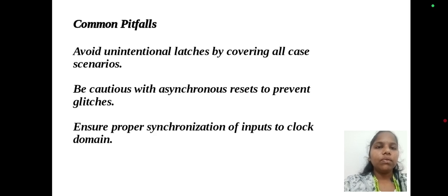Common pitfalls. Avoid unintentional latches by covering all case scenarios. Be careful with asynchronous resets to prevent glitches. Ensure proper synchronization of inputs to the clock domain.